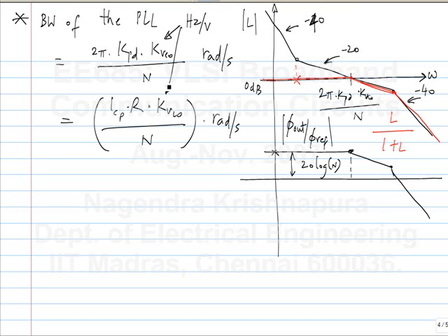So if you have to design the frequency synthesizer to settle within a given amount of time, you will have to take care that the bandwidth is large enough. Such a requirement may come about especially in a radio. In a broadband communication system it may not, because usually you don't have multiple channels which you have to switch. But when you have a radio like a GSM radio, you have different bands for transmit and receive, and you use the same synthesizer.